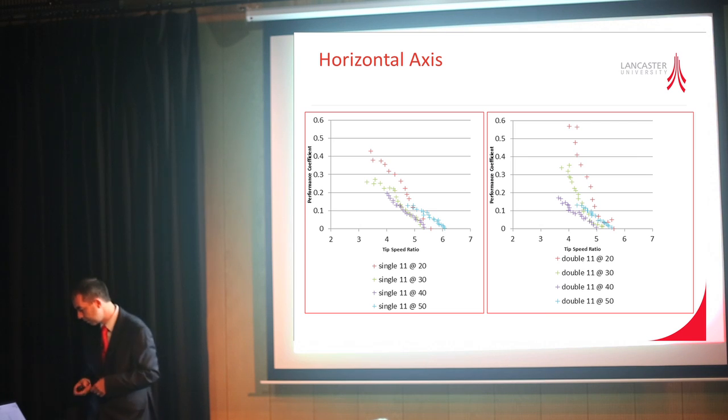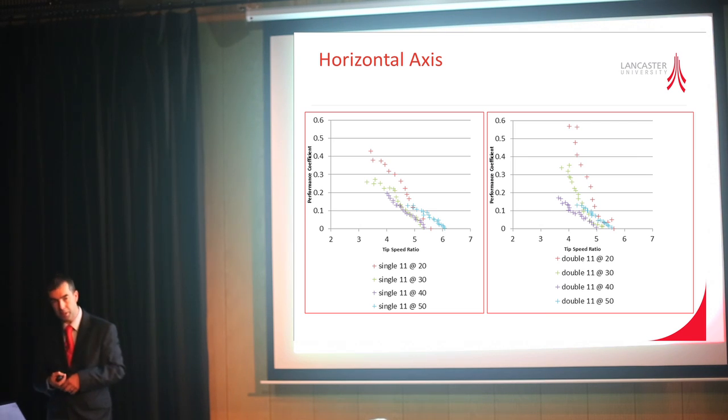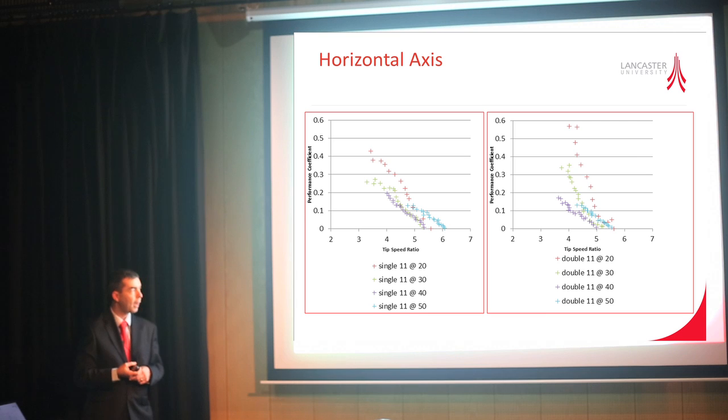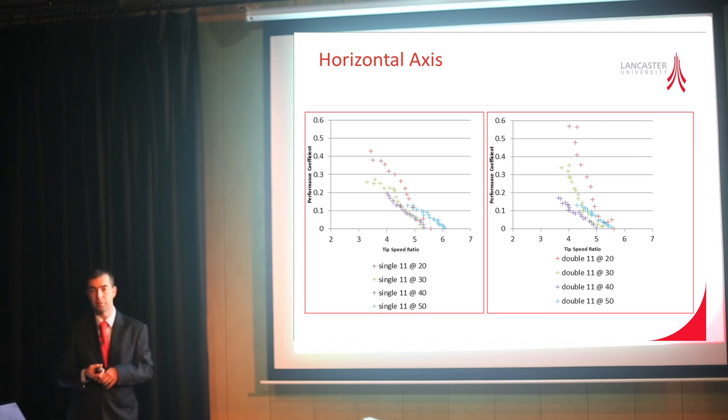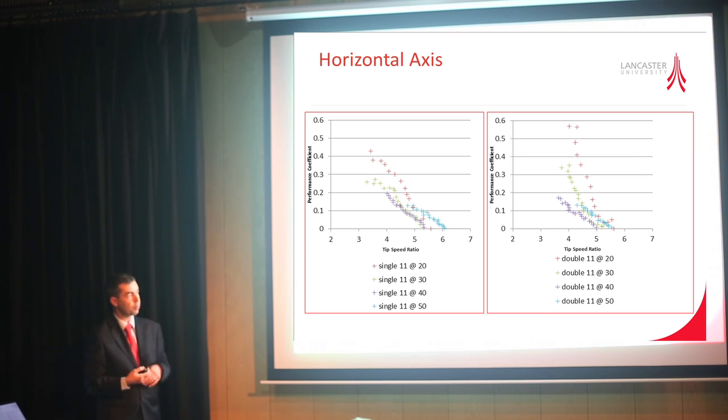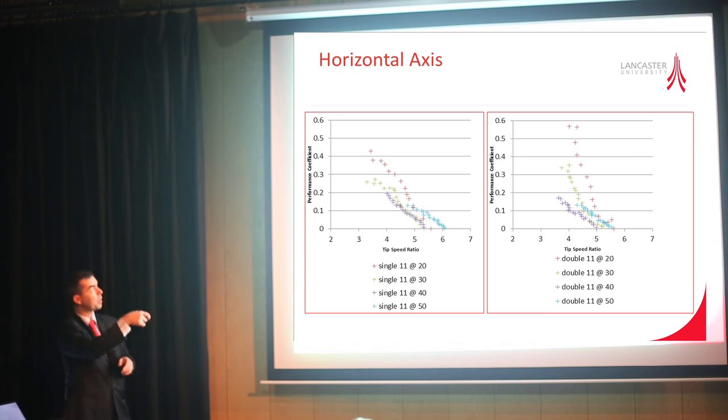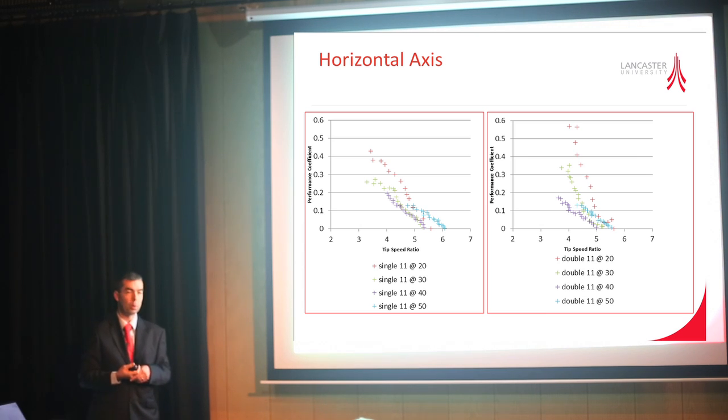Similarly, looking at horizontal axis turbines, we've also been doing some work, but it's very much at the early stages at this point in time. We've modelled a simple split aerofoil section against a more conventional aerofoil section, where we do scale model testing in our tank at the university. And here we see the performance characteristics. Typically turbines are defined by their tip speed ratio and the coefficient of performance. The performance coefficient is essentially how much you can extract from that body of water.